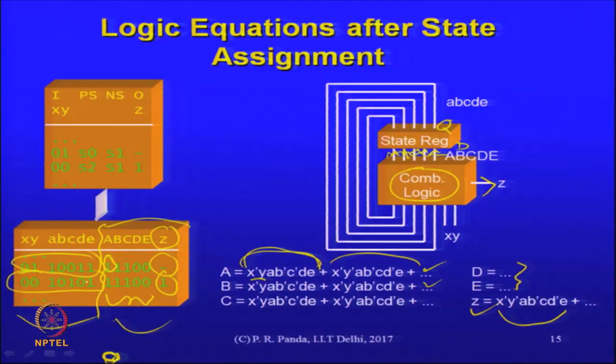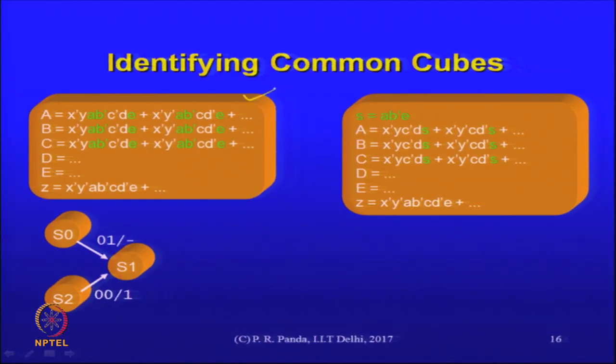Of course, as of now I have only specified very explicitly what those expressions are. This is not an optimized form of that expression, but it is just like the specification of a Boolean function. So, that we start from here. Any questions about the way we form this? This is of course an important first step in any further arguments that we make. Those were my set of expressions, and let us get to identifying optimization opportunities in those expressions. Optimization opportunities for us right now are the process of identifying common cubes, because we said that that is what we can concentrate on. It is easier than finding general common sub expressions. Common cubes, if I look at that expression for A, I see that there is a common cube between that expression and this expression.